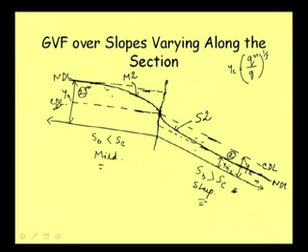Now if we recall the characteristics of the S2 profile and the M2 profile that we discussed, we are getting what we discussed about the boundary point at downstream, and here in case of S2 at upstream. So it is behaving in the same way, and we are getting the total flow profile. As a surface we may see one profile going like that, but so far as the name is concerned, we have two names for two parts.